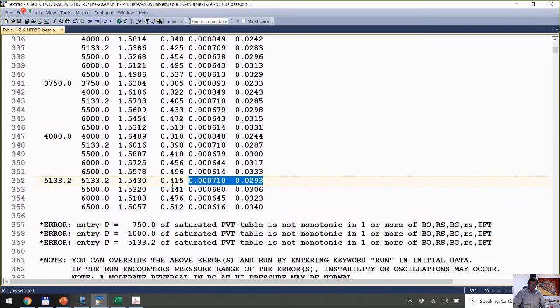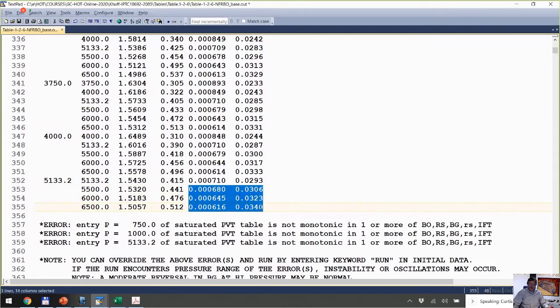But if you take that initial gas to undersaturated conditions, then you get undersaturated gas properties as necessary. So you can initialize the reservoir up to 6,500 psi. Okay, you couldn't run this model with an initial pressure of 8,000 psi because it wouldn't have the properties for the gas.